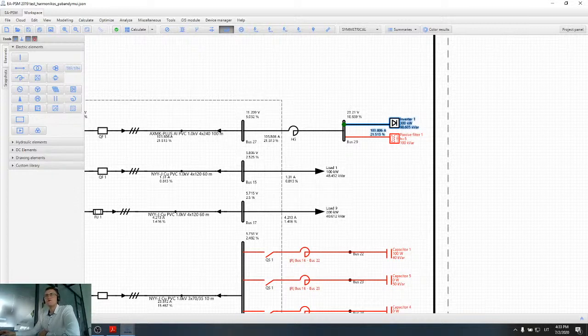Actually, you never know how fast equipment will deteriorate. You can check from time to time, but usually energy bills show that your capacitors are not providing enough power. So just based on energy bills, you check if the reactive power consumption is not too big, and that's okay. If it is very big, then you have to take some action to reduce it.